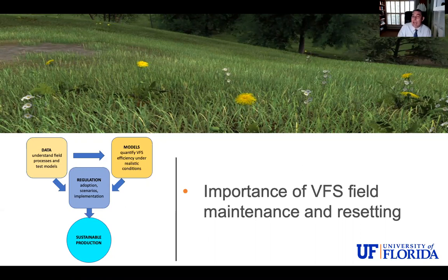And then you need to realize that every so often there will be a big event, with a return period of, say, every 10 years on this field. If you get the largest event in 10 years, you will get a lot of sediment and a lot of water, and probably you will cover at least part of your buffer with sediment. It will just be inundated. So you need to expect, every so often, to reset the buffer, which means you are going to plow it, level it, and then reseed it, let it grow, and then reestablish it.